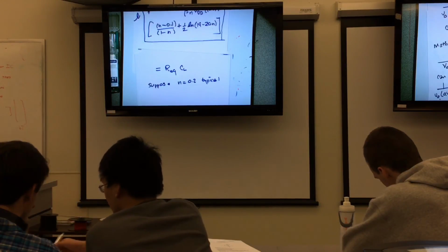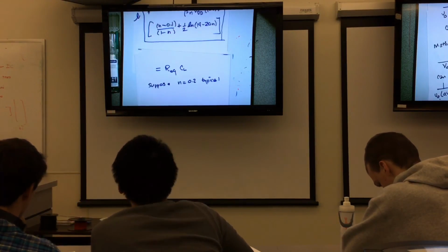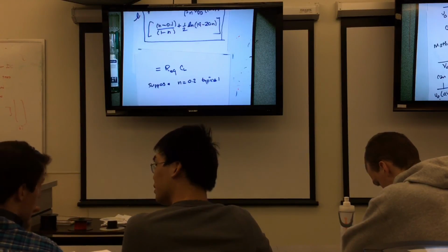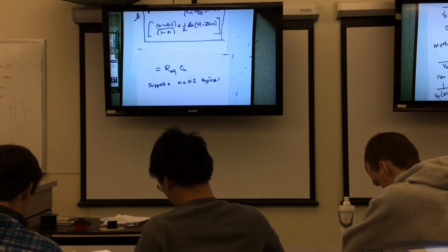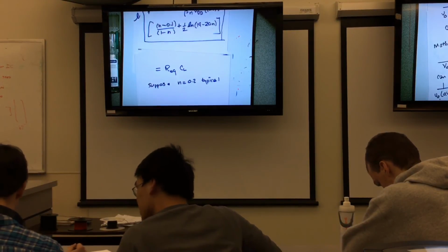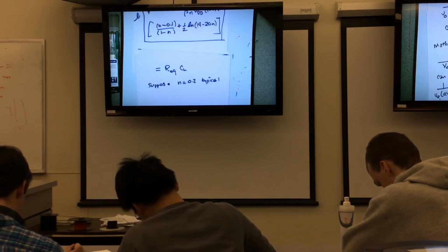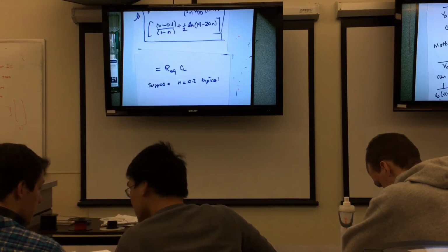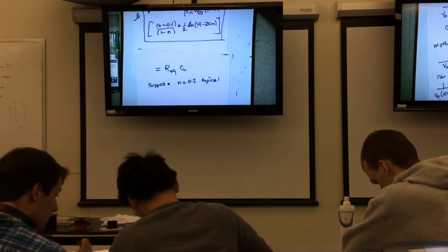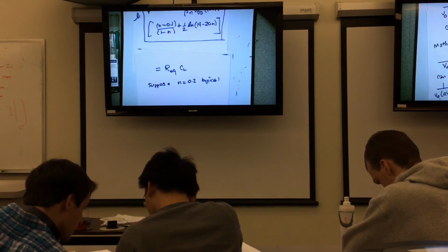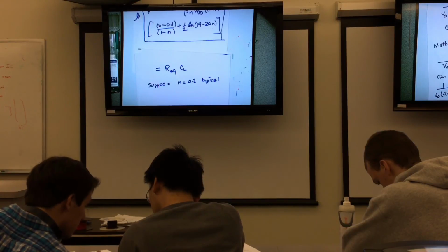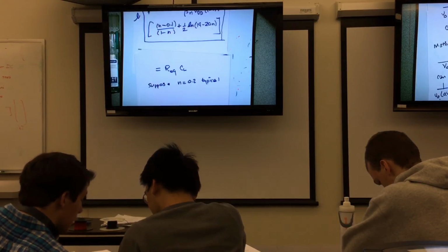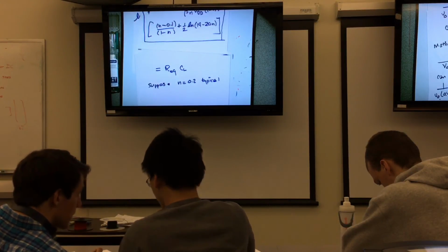And it's hard to keep doing it, because one of the things that's happening now is we try dropping the voltage to get the power down. We've got to do other things to speed this stuff up. One of the ideas was using a better oxide so we can boost the currents up and we can drain the current off faster, all the obvious stuff. We're no longer able to keep squashing the VT down, reaching some fundamental limits on that. Somewhere around a volt, VT is 0.2 of a volt, we're not getting much smaller than that. That's pretty much it for CMOS.